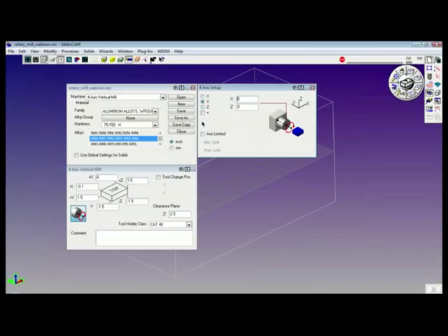We can place it along the y-axis, positive or negative. And in certain situations, we can even use the z-axis where we're rotating around z with the turntable. Placing it upside down is a little bit inconsistent with what we can do on a machine, but the choice is there. I'm going to select X minus, placing my fourth axis on the right-hand side of the operator as he approaches the machine.